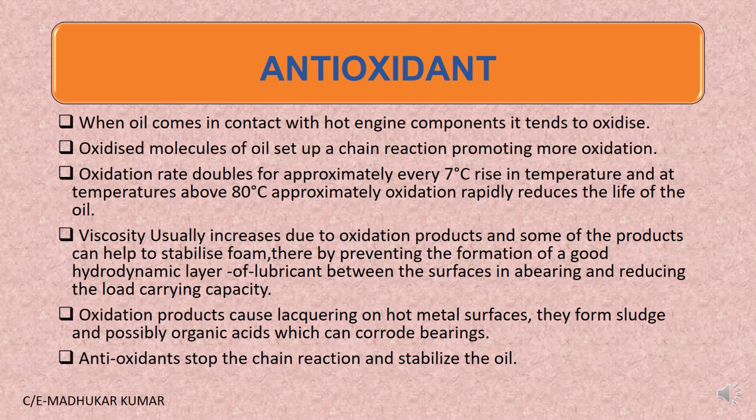And do you know that the oxidation rate approximately doubles with every 7 degree rise in temperature? At temperatures above 80 degrees, oxidation rapidly reduces the life of the oil. So the complete property of the oil is lost, and finally you have to replace it with new oil. Viscosity usually increases due to the oxidation products.